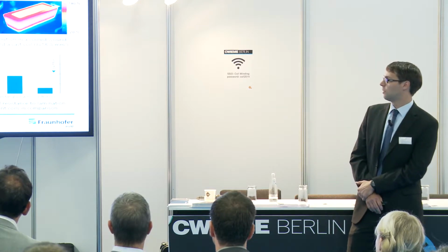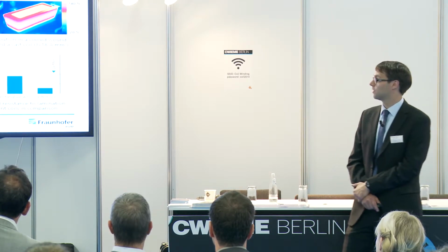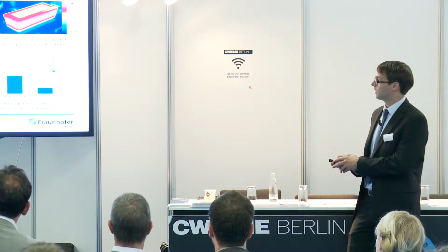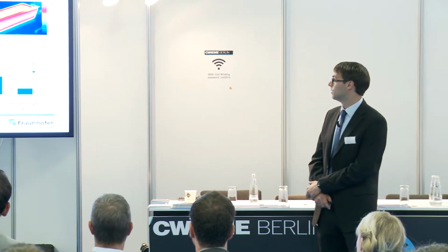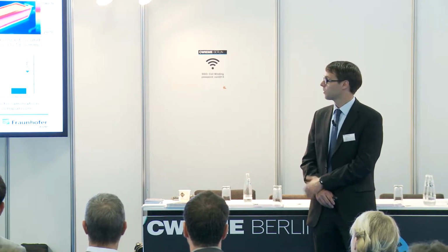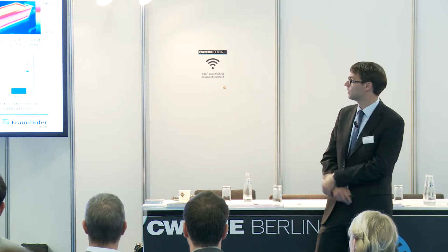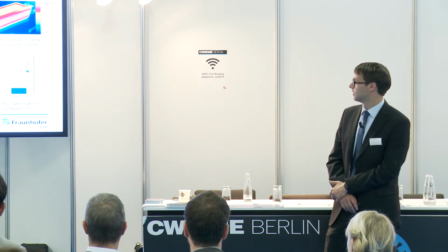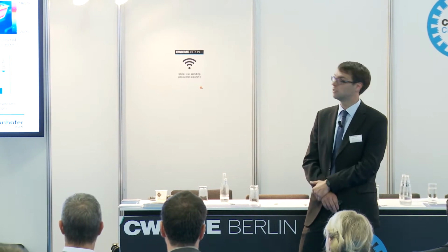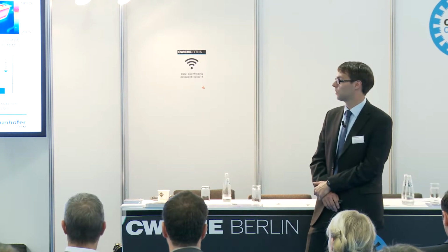And additionally to the electromagnetical advantages, the flat conductor arrangement of the casted coils offers some thermal advantages. Again, the flat conductor arrangement leads to very good heat flow from the coil to the lamination stack. We did some measurements to quantify this effect. And it came out that the thermal resistance of a casted coil with a one-dimensional conductor arrangement can be decreased by about 80% related to a wound coil.